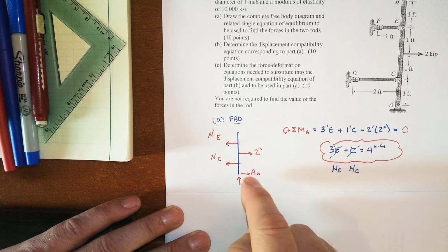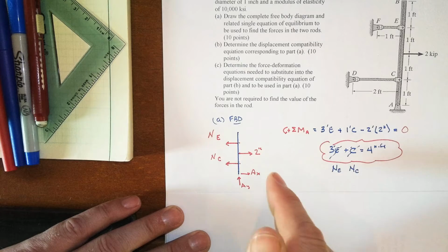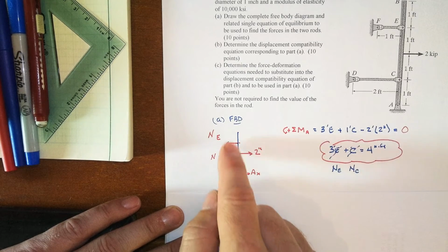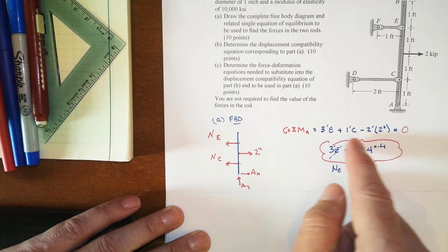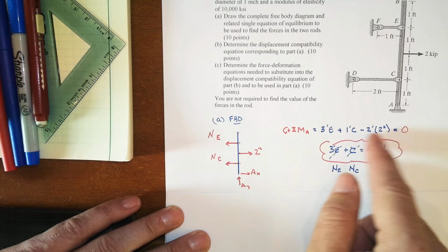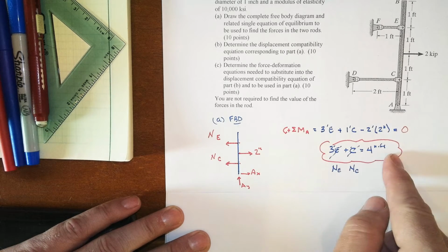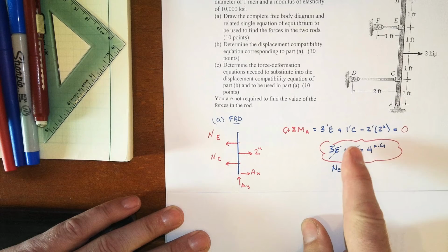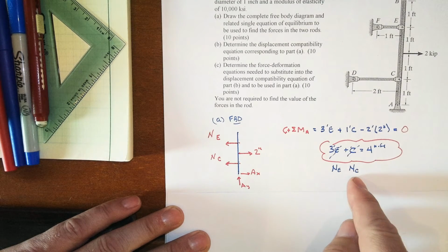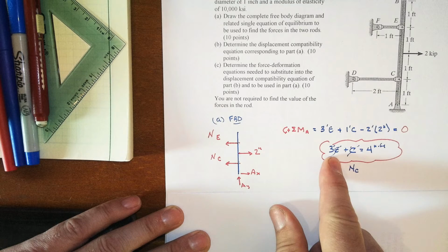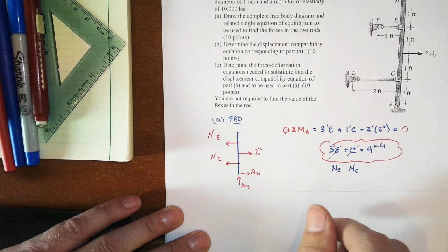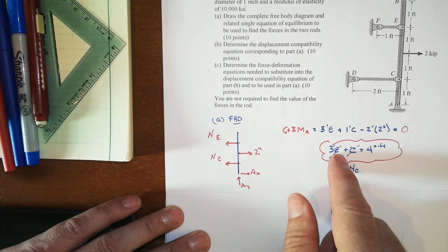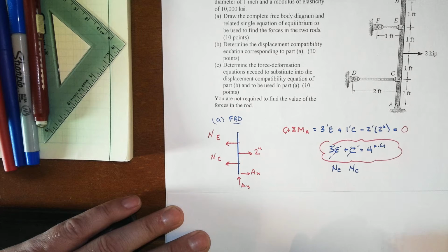So who cares what the values are? Ultimately, I can write an equation that only involves these 2 unknowns by summing moments about point A. And so the force at E, force at C, they have their moment arms, there's the moment arm associated with the applied force, and we get a nice simple little equation. Now you see I crossed out the E and the C and put NE and NC, because I realized after the fact that capital E is also our elastic modulus, and that's going to show up somewhere else. So that was a poor choice initially of the symbols for the forces. But here's our answer for that basic equilibrium equation.